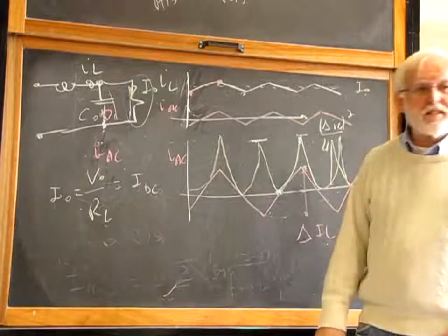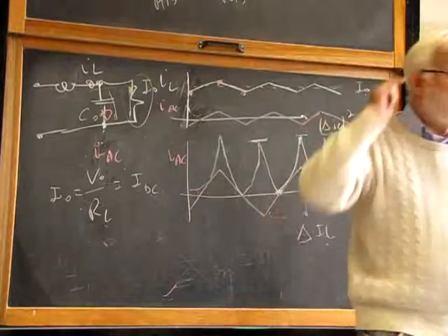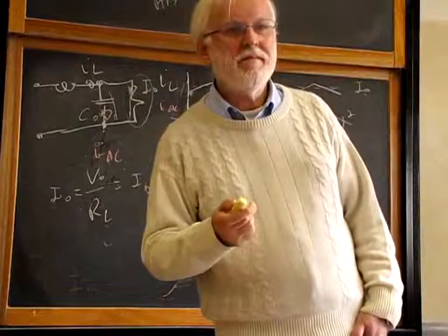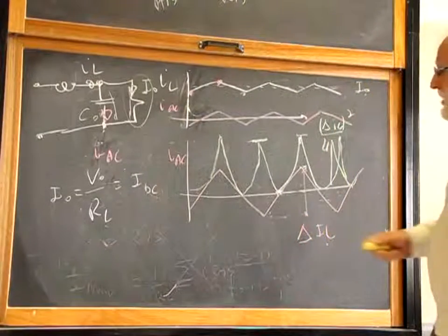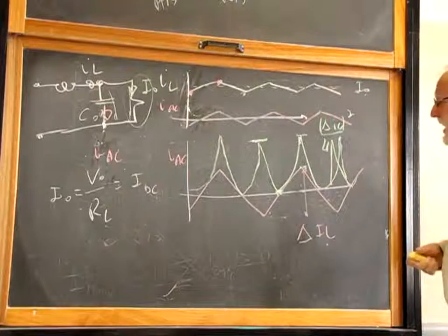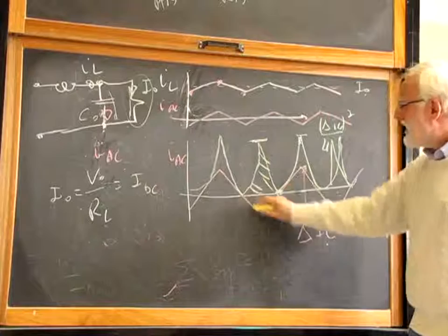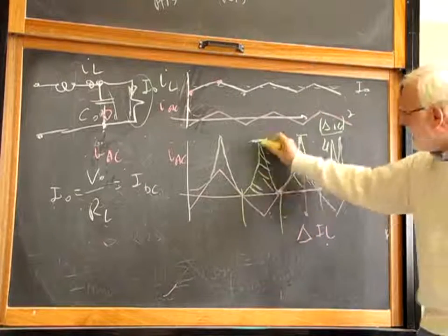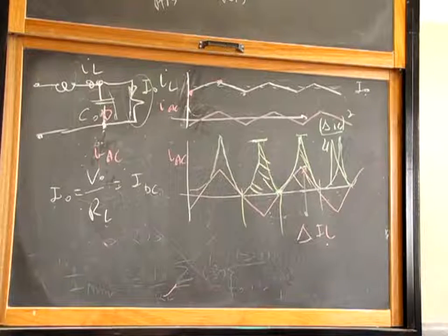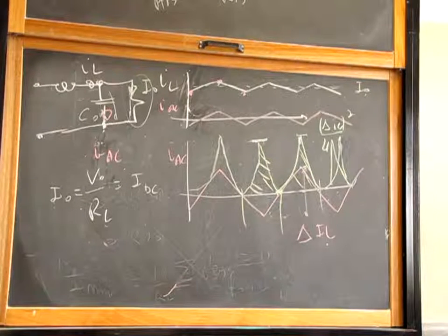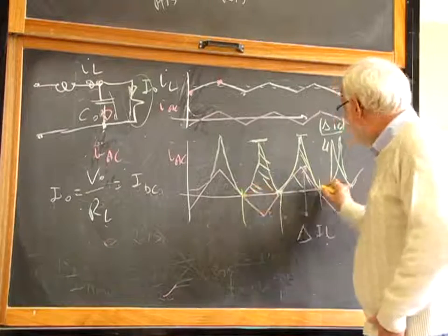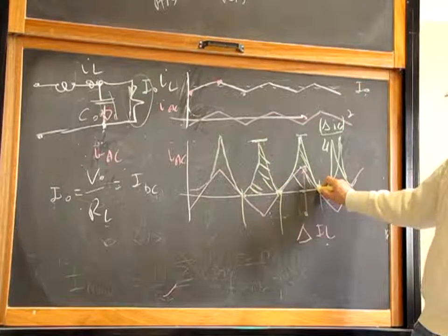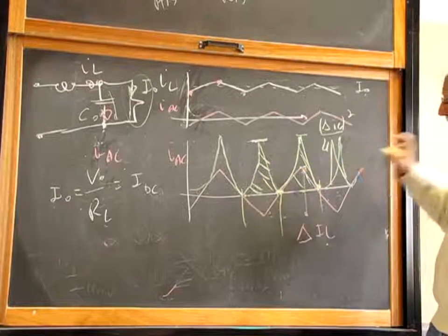Second step in our RMS recipe is M, mean average. So we have to take this area and spread it over one side. What shape is this? It's a parabolic triangle. How much is the area of a parabolic triangle? 2/3 base times height is right. It's 2/3 in the fat triangle, it's 1/3 in the skinny triangle. So this area equals this base from here to here, or this base from here to here. Those triangles are exactly all the same.